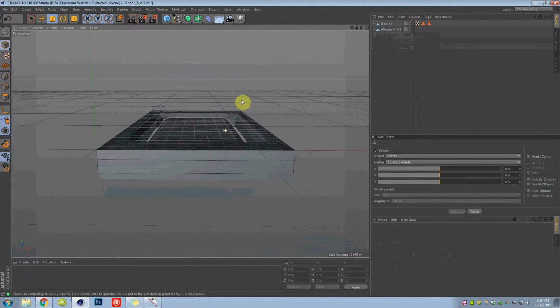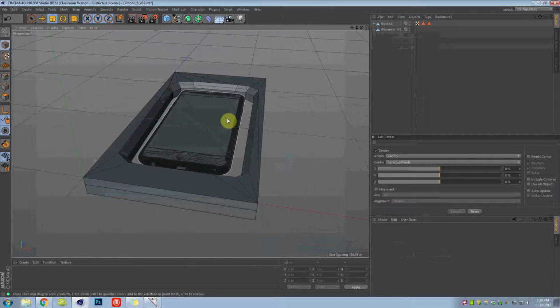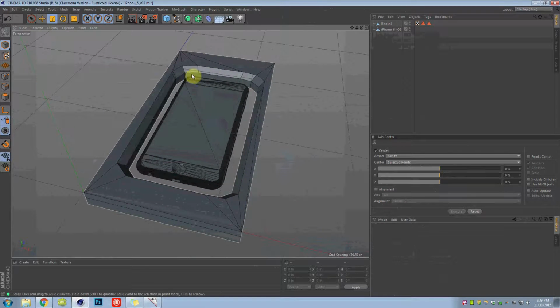Now, the lattice work. Kind of important, because imagine the mill cut out this shape and then would go to cut other shapes. This would start wiggling around from vibrations, get hit by the bit, maybe go flying, at the very least get damaged. It's important to have connecting structures on the side.